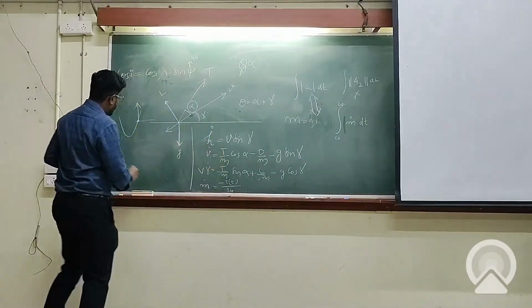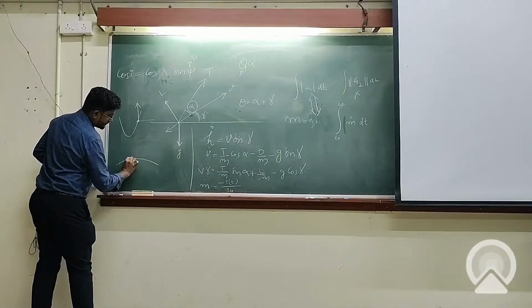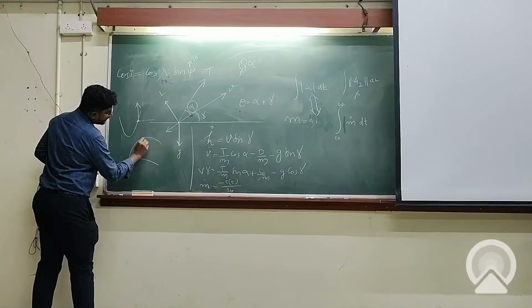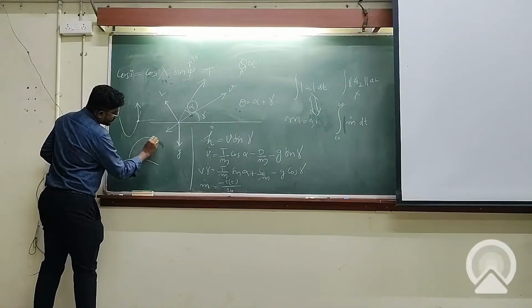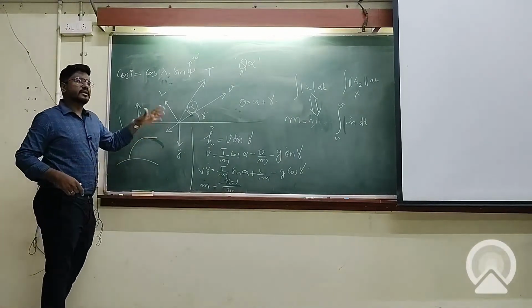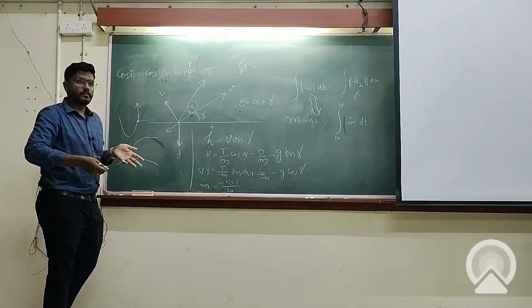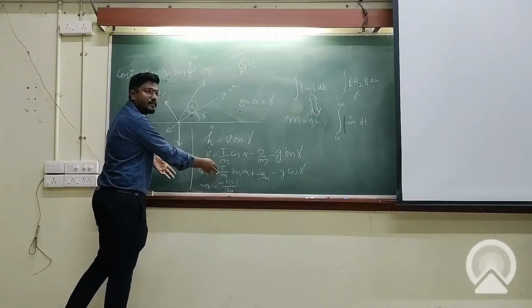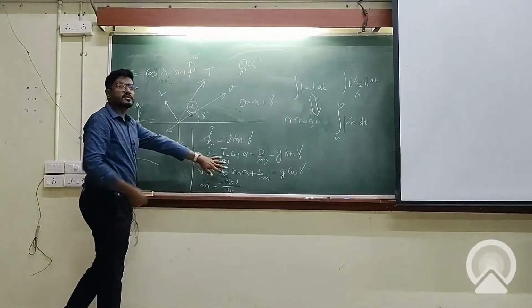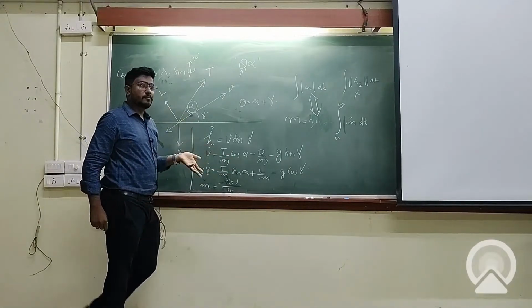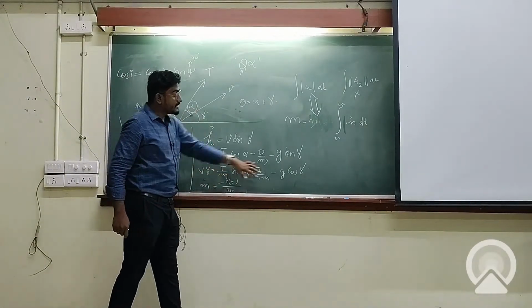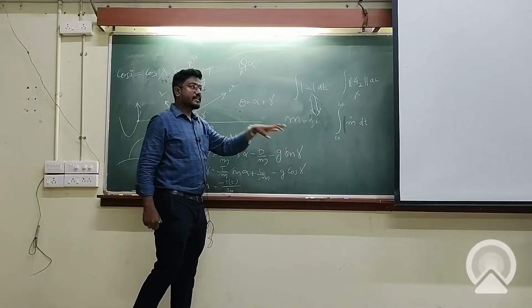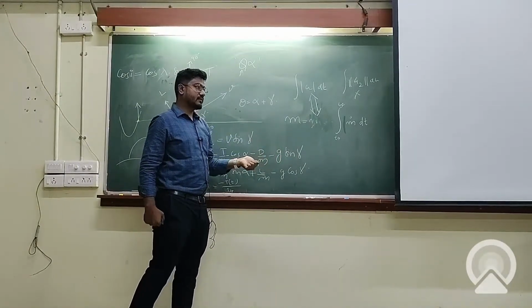Basically, we are lifting off from the surface of the Earth, then rotating the velocity vector to achieve a flight path angle of 90 or 0 degrees, depending on where you measure it. But there is no thrust acting in the process of rotating the velocity vector. That indeed is optimal, and hence the name gravity turn. Gravity is actually turning the velocity.